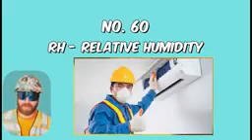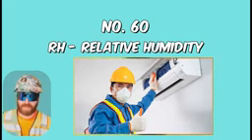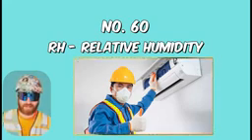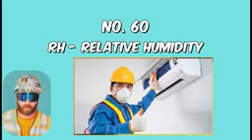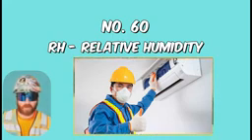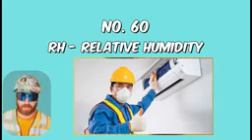RH, relative humidity, simple but important. When you start finishes on a project such as drywall or installing casework or other products, the building needs to be acclimated, as do these products. If they're not, you can get cracks in the wall or warping in your building materials. This is why buildings are temporarily heated in the cold and cooled in the heat to maintain schedules throughout different seasons based on the region you're building in.